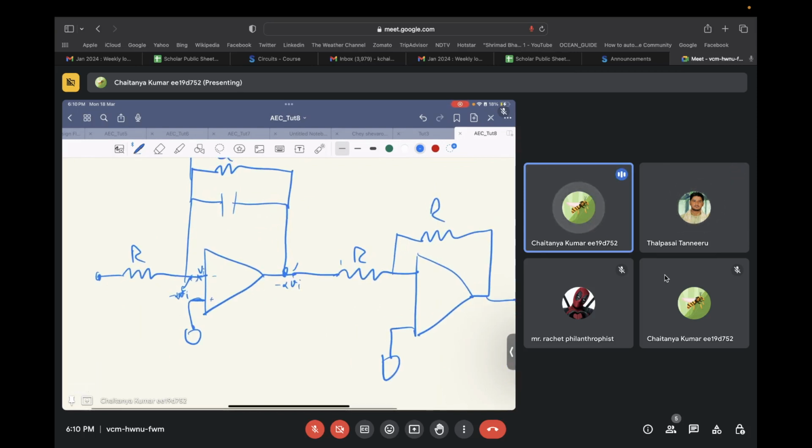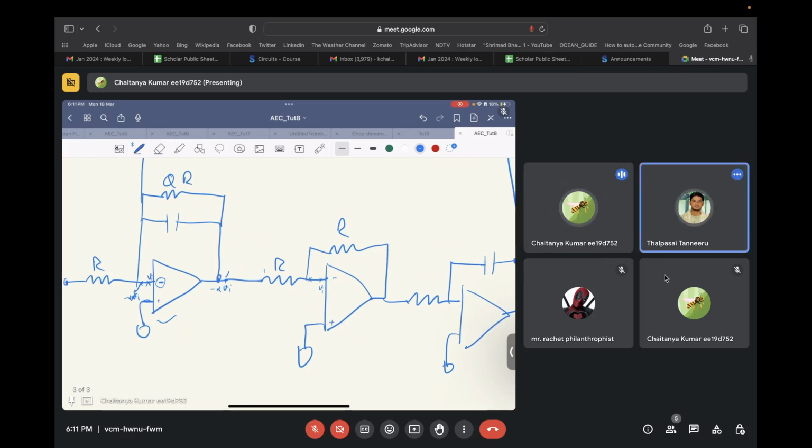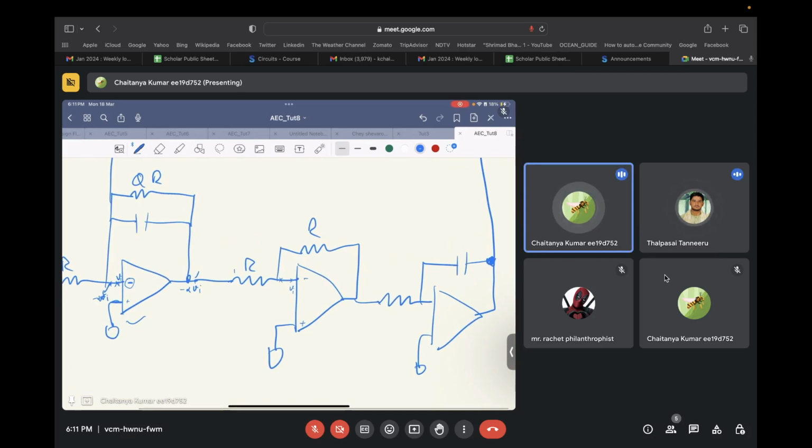So basically, if you put an inverting terminal at this node, whatever goes through the loop, whatever comes back, is a negative of what you have given. That means your signs are correct, and this particular loop is stable and in negative feedback. Similarly, for this loop, if we disconnect over here and apply some Vi, and we have a negative sign over here,